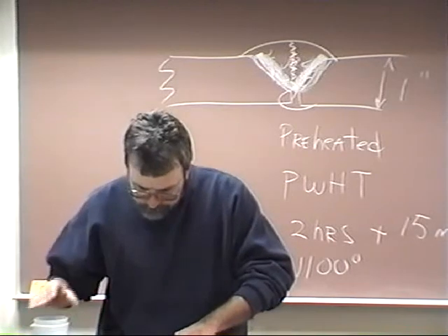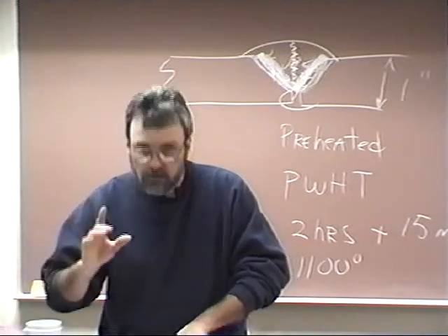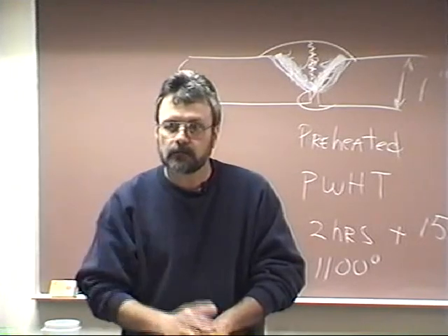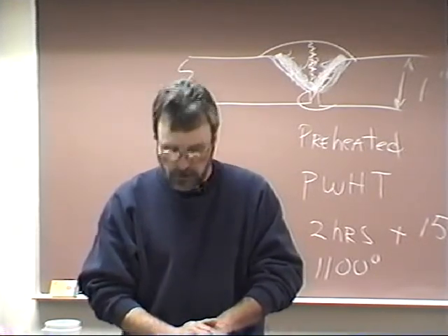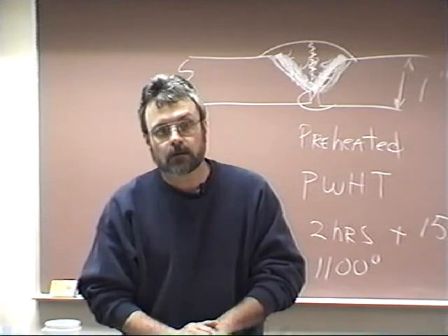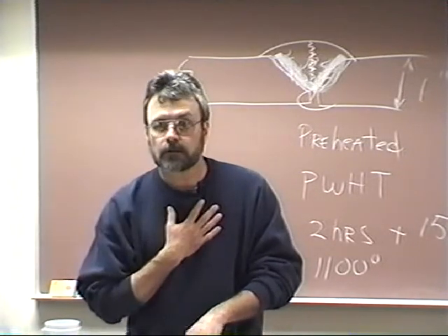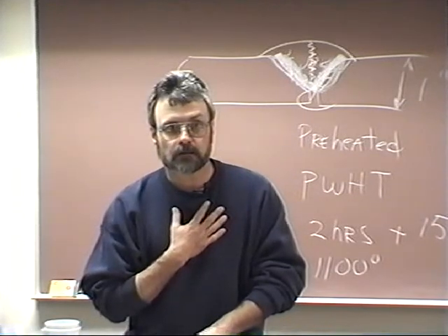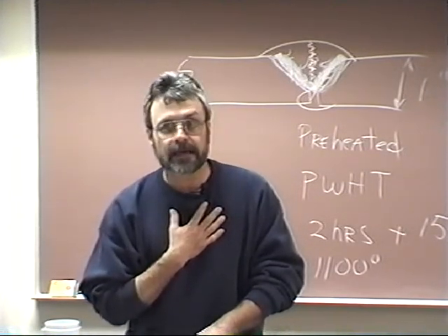And what's the most important thing in making a repair? Making sure that you get it all out. A lot of times I will ask a welder to get me so I can come and verify that he's got it all removed. Because I deal a lot with X-rays, a lot more than the typical hand does.